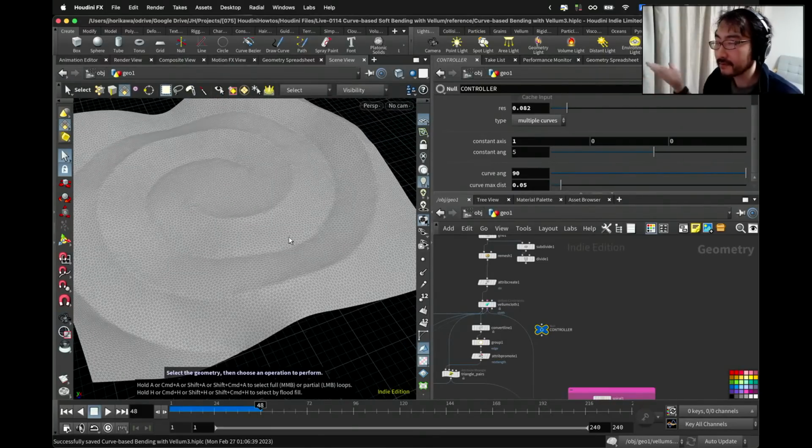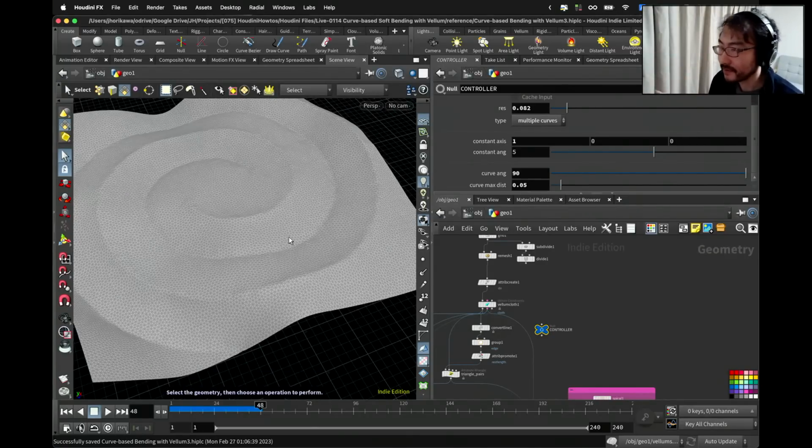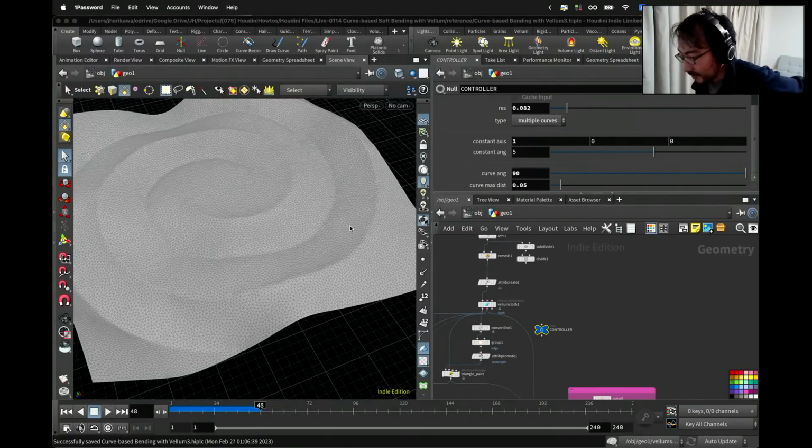And the thing is that it doesn't really limit it to curve, but the reference could also be a surface or any equations or geometrical information could be used to calculate the bending. The important part for this tutorial here is how you could calculate the rest lengths for the constraints for the Vellum based on the vector. So it could also be like a vector field.